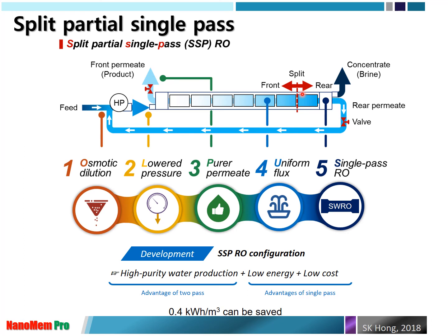But you can split within your one pressure vessel. You collect your permeate at the end of your RO module, and the rest goes to your feed water side, which means this seawater will keep increasing in salinity. So the permeate quality at the end has very high salinity, and therefore if you mix it with the front module permeate, your overall water quality is not as good as your initially collected module permeate.